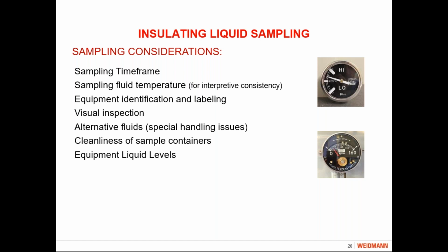If the oil level drops below the top of the active parts of a transformer, that can cause both dielectric and thermal problems that can lead to a rapid transformer failure. So it's something you want to avoid. We understand that some smaller transformers may not have gauges on them. You may not know what the liquid level is. You're just going to have to do what you can to ascertain that over the years you haven't taken too many samples out.